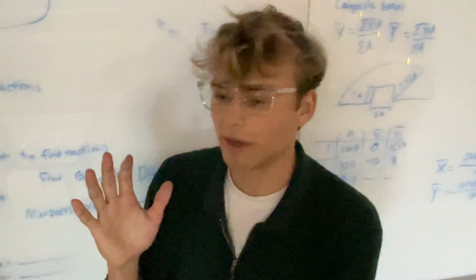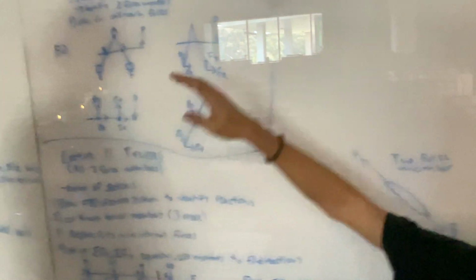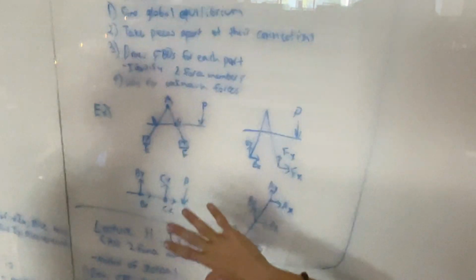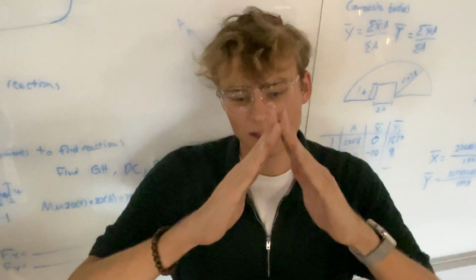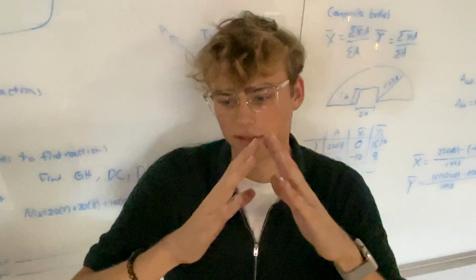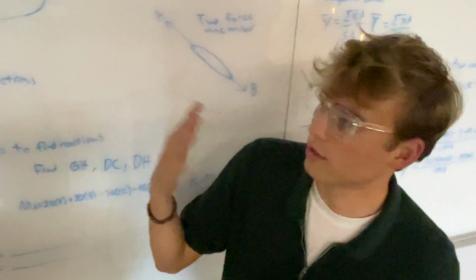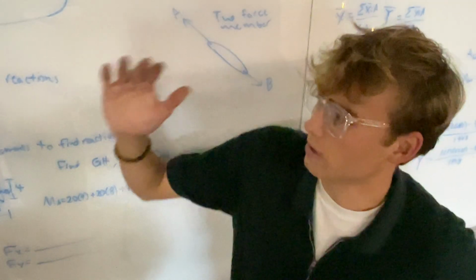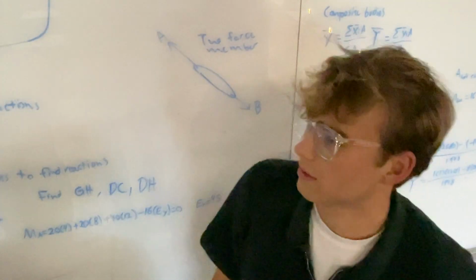Can I just add in, I think this was on the midterm, the take-home part of midterm 2, which is stumping us a little bit. It was a similar A-frame, similar to this. And I think there was not a joint here. So like this problem, you can totally take it apart, but if it's welded together, you can't take those 2 apart. So in the midterm, it was welded like this, so we couldn't split those apart because they're welded, so their forces are gonna be internal. But that's just something to keep in mind. Usually the problem will make that clear. You could probably ask the TA, but where there's joints, take it apart. But if it's welded, if it's one piece, don't be taking that apart.